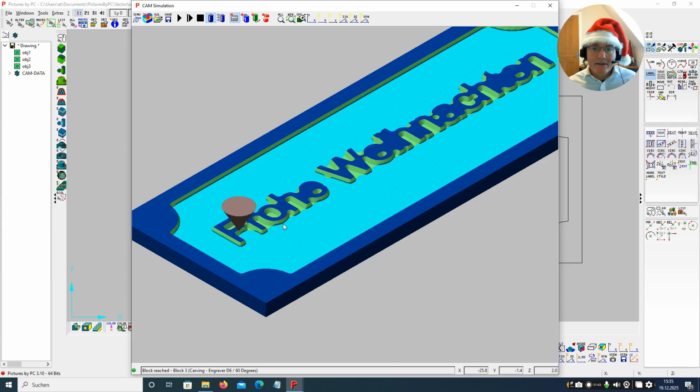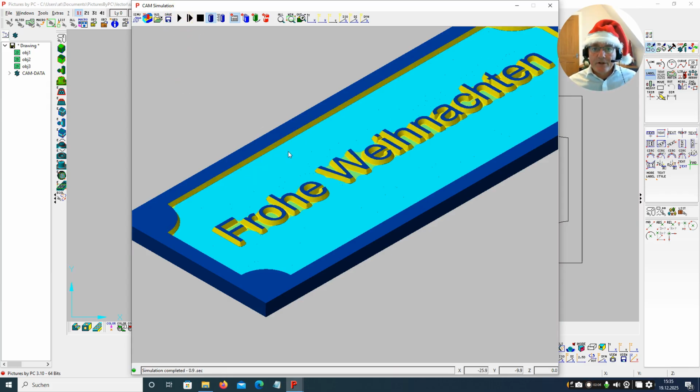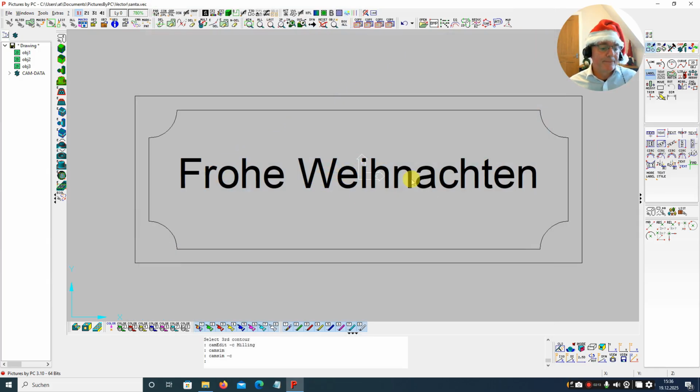So what it's doing automatically, the software is generating 3D toolpaths and ramping the tool up in the corners to create the sharpest edges, and in the areas where it can't get through because of the diameter of the tool or the angle, it's changing its height to machine as deep as it can. So we're achieving the result at every part of the contour here, even though the tool can't get fully through. And that's professional carving, and we can do that on freeform. We can do that as a 5-axis simultaneous toolpath if we wanted to.